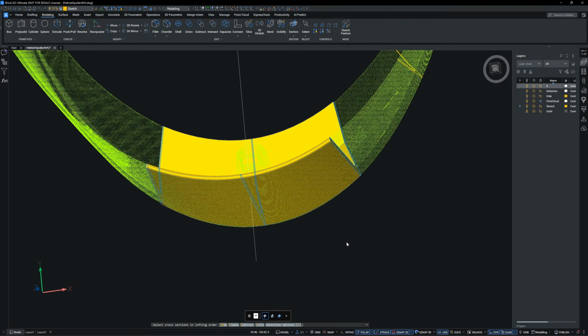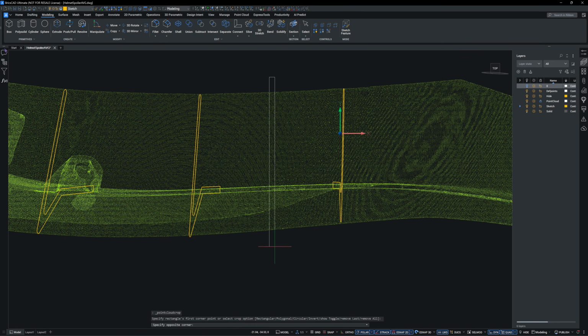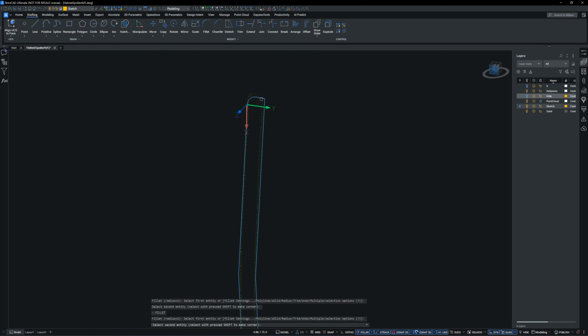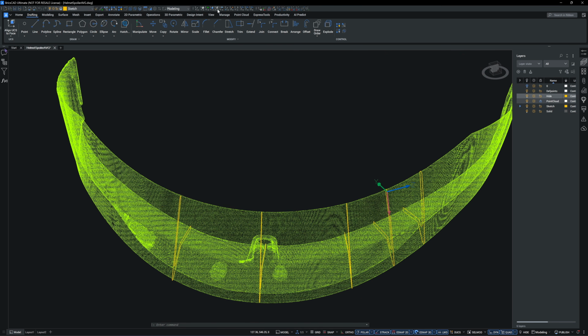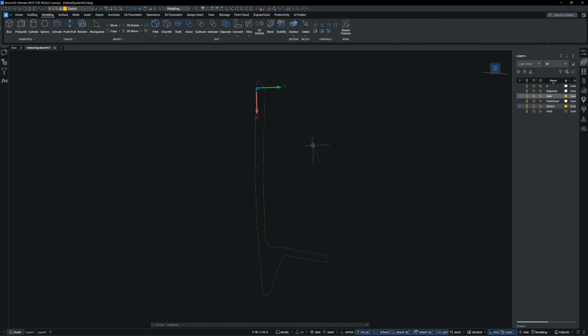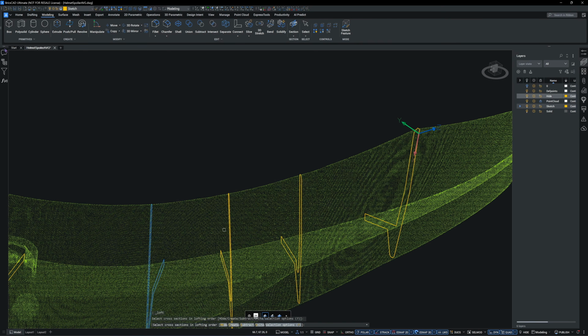I'm testing the loft model, and you can see there is a gap between the second and third sketch profile. So I will add another sketch profile in between to close the gap. For this part of the model, I won't use guide rails because I want the loft body to be as smooth as possible. Now we have an issue here.